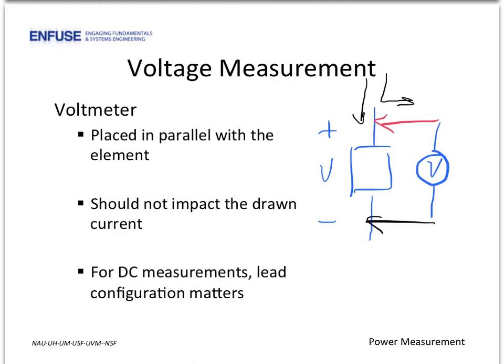For AC circuits, your voltage measurement will be the RMS voltage, and that's always positive. However, for DC circuits, you need to ensure your negative lead is located at your reference point. Your multimeter will have a red and black lead, and by convention, the latter, that is the black, will be your reference.